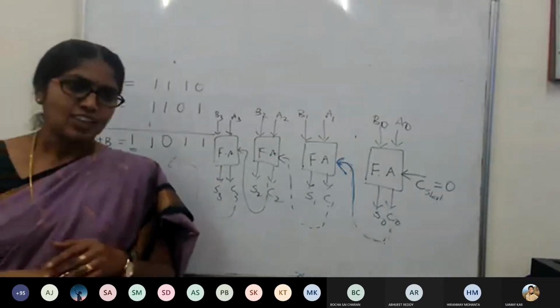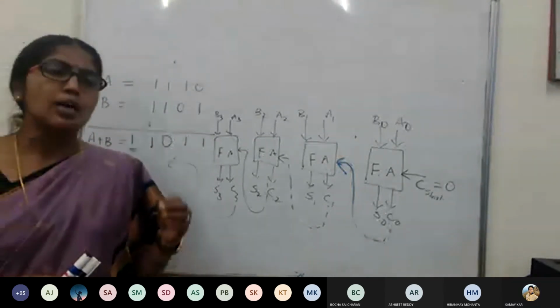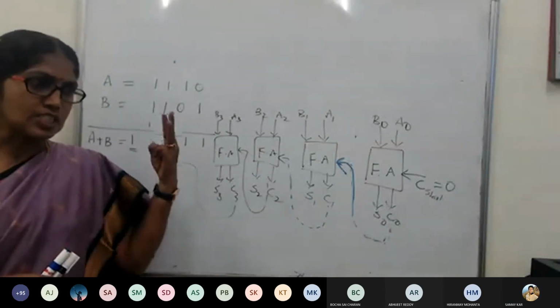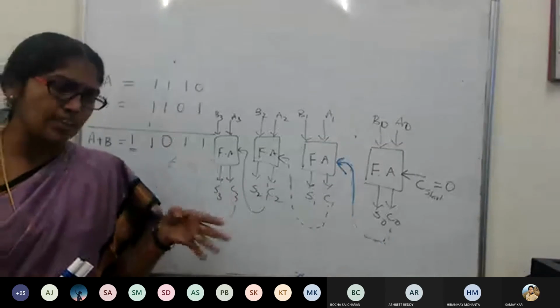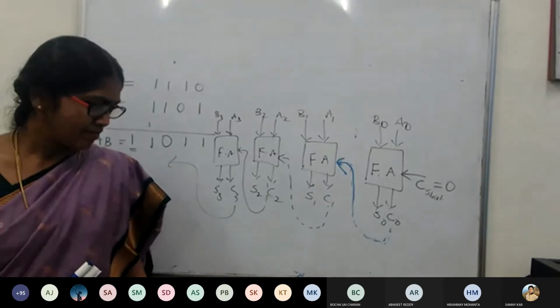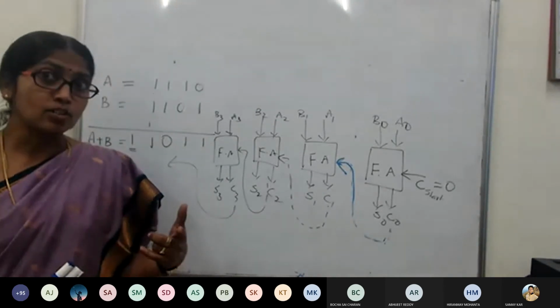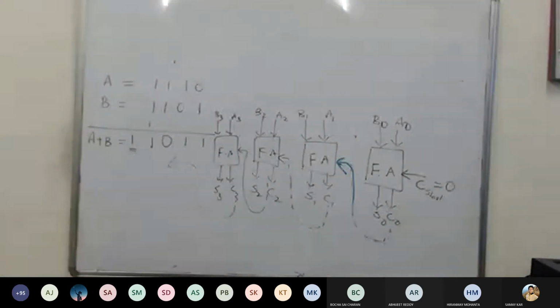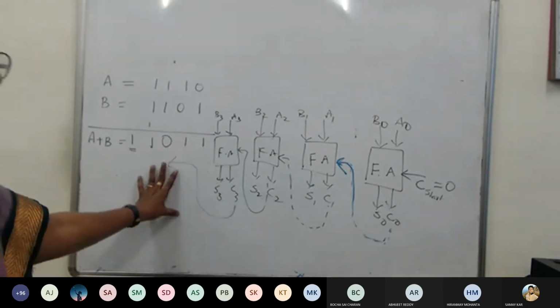Yes, ma'am. Right. So the only flaw, nicely observed, is that the carry became dependent. The third bit, which is acting as one of the inputs to the full adder, is becoming dependent on the previous one. Is there something wrong? Is that correct? So we are fine with this now? Yes, ma'am. We have a sequence now. We can have a binary parallel adder, but there are some flaws with that. So this was the initial design.